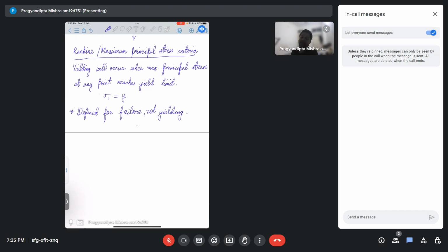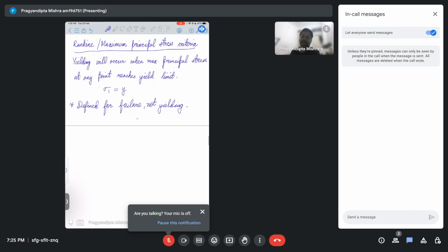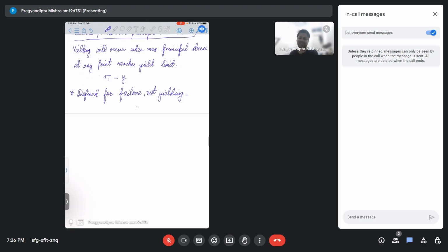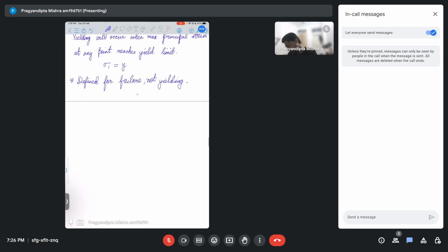What that means is that you are only looking at the hydrostatic state of stresses, and you do not have any plastic region. You're not playing around with the plastic region. So you are completely ignoring all the shear stresses, etc., which can influence the plasticity. Therefore, you will have an elastic region and direct failure after that. So only the hydrostatic state of stresses you are looking at.